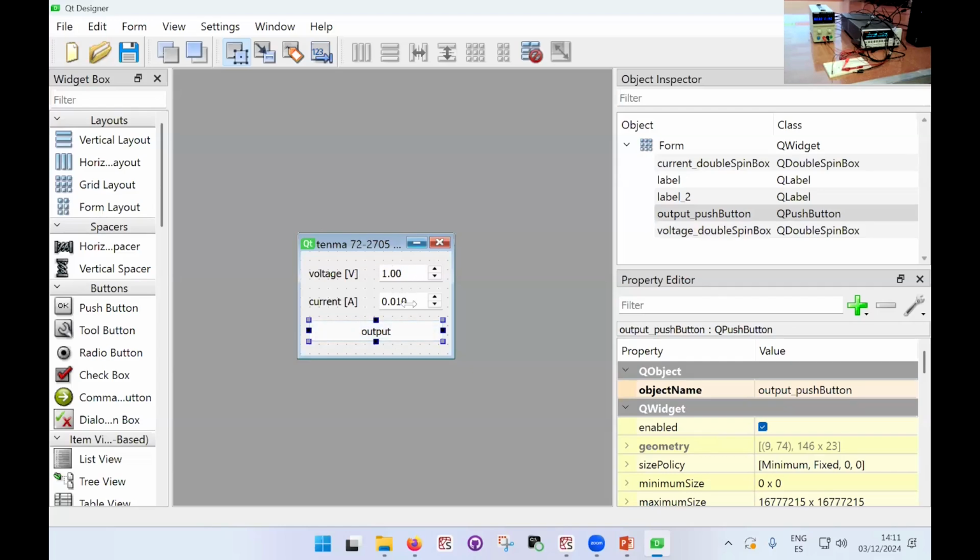The way this power supply works is that we can operate in a constant voltage or a constant current mode, depending on which is reached first of the two settings. So if I say that I want a current of, for example, 20 milliamps, I can turn on the power supply, and it will make sure that I never exceed 20 milliamps. But I can go below 20 milliamps. Well, you'll see that in a minute. But if I start to supply a voltage that would lead the system to have more current than 20 milliamps, the power supply will actually not do that.